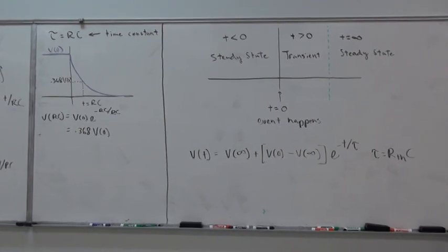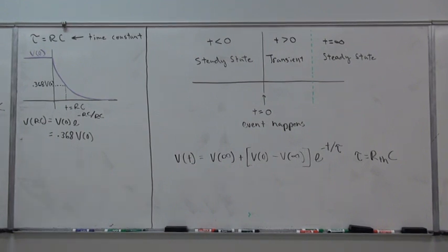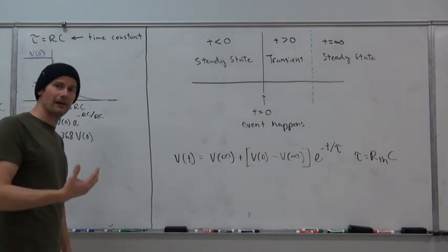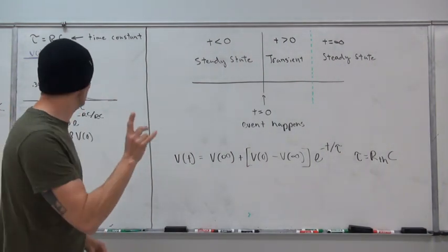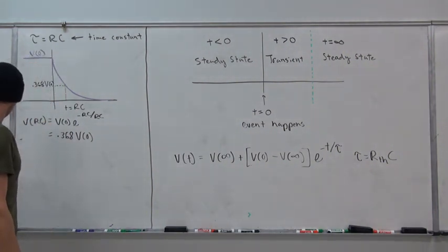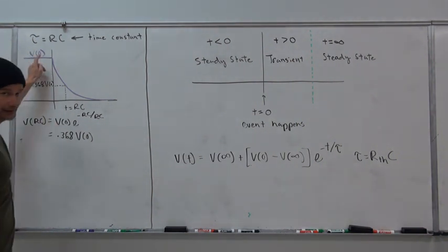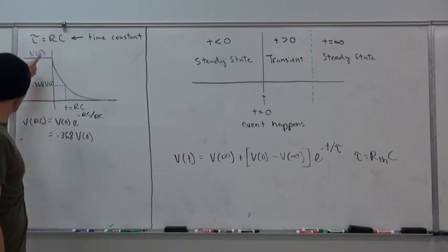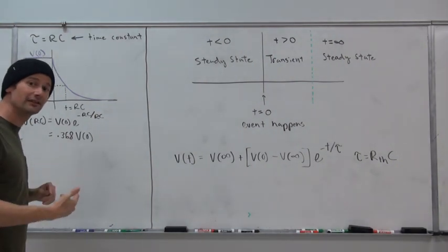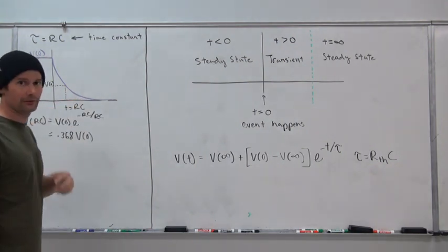All right. So we derived here that the time varying voltage across that capacitor in a source free circuit is dependent upon the initial condition that was built across that capacitor. Well, e to the negative t divided by RC means that it's going to decay in nature. So we start off at its initial condition. Because this is source free, there's no other source to excite a voltage across that element, so we decay out to zero and it dies.